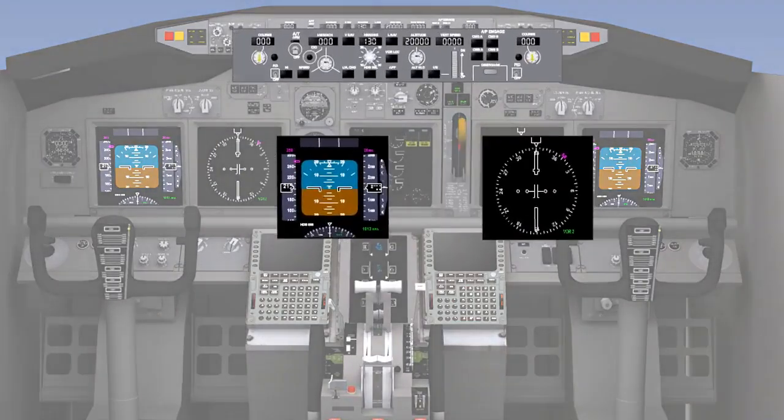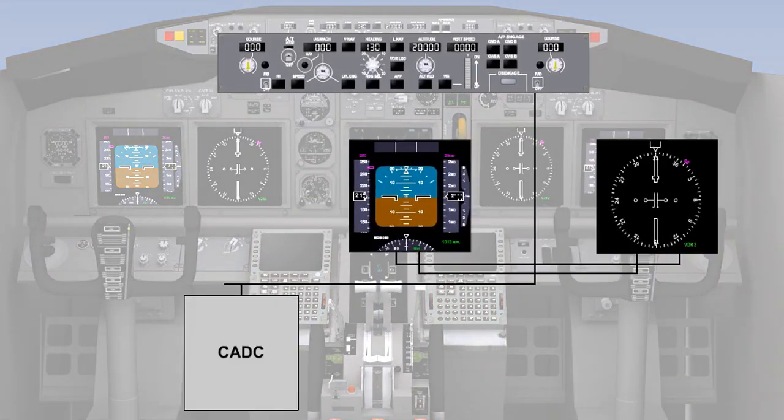To use the guidance functions of the autopilot for long-term navigation and speed control, the autopilot needs to have current navigation and air data information fed into the computer. When the respective pitch or roll command mode is engaged, the computer couples the target value with the current value to generate a steering command to the inner loop. The following systems or components provide continuous inputs to the flight control computers.